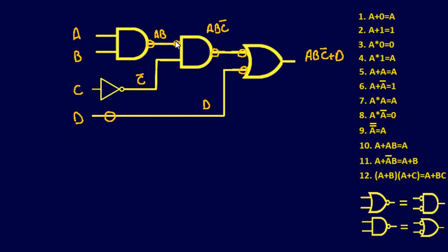Well, the way we can fix that is actually, as we discussed earlier, we can make that an inverter. So anytime you have an extra bubble, you can always throw another NAND gate in there to compensate for that bubble. That's what I plan on doing down here too. And of course, we have an inverter right here, so instead of adding a bubble here and trying to cancel out, either way we have to add another inverter to compensate for this guy. So, looks like I'm going to have at least 3 NAND gates that are going to be shorted at the input to create inverters. So there's going to be one here, and there's going to be one here.